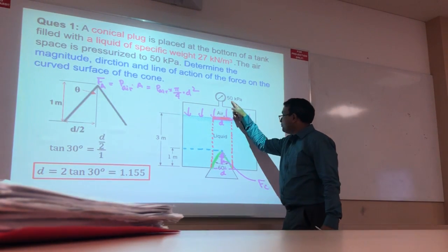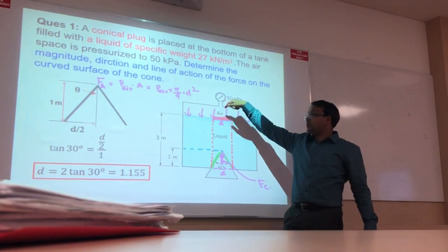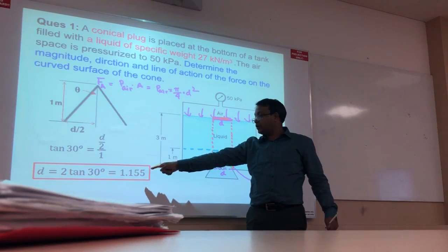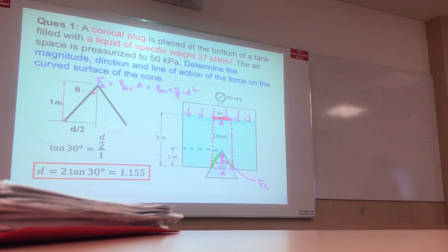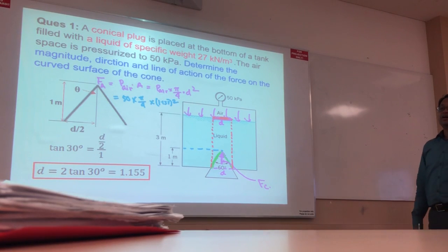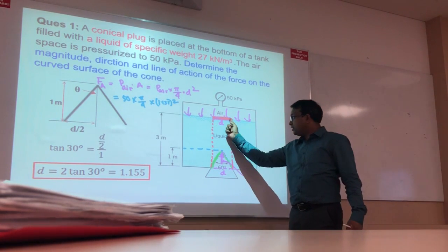Because air pressure is 50 kilopascal. 50 kilopascal times pi by 4 times 1.155 squared, I can get the number, which is the air force. So I can write 50 kilopascal times pi by 4 times 1.155 squared. Separately they can ask you what is the force given by the air. Then you have to calculate this area.